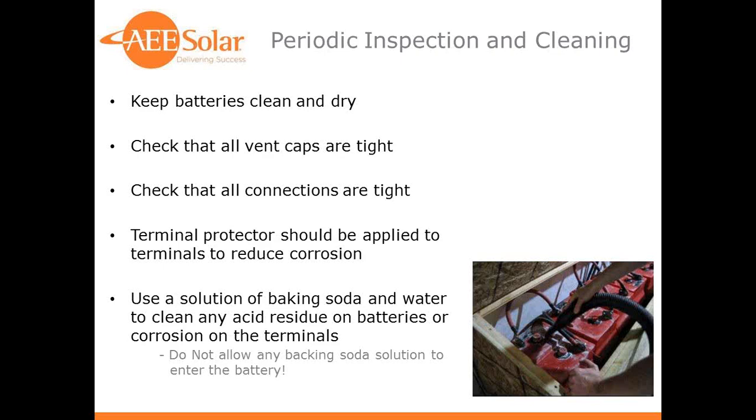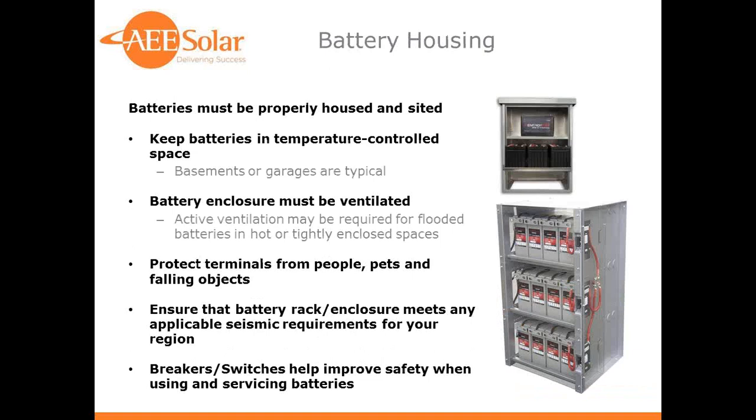There are products on the market specifically for this purpose, and we also carry that, so you can get that through us. And again, using a solution of baking soda and water to clean any acid residue on batteries or the corrosion of the terminals. But don't allow any of that solution to enter the battery, obviously. Not only would that neutralize some of the active material in the battery, but it would likely cause a fairly violent bubbling of it. And hopefully you have your safety glasses on, but hopefully you don't get anything in there. So make sure you don't get any baking soda inside the battery.